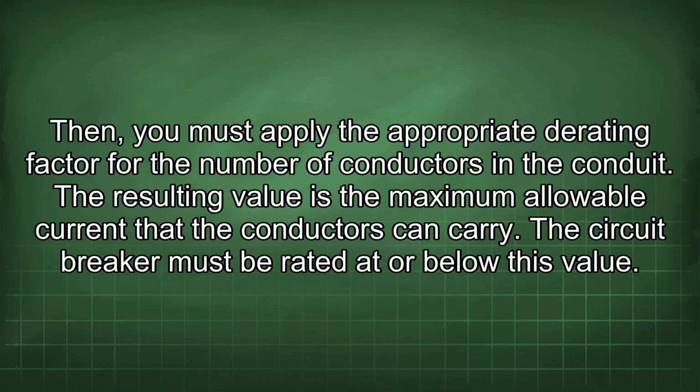Then, you must apply the appropriate derating factor for the number of conductors in the conduit. The resulting value is the maximum allowable current that the conductors can carry. The circuit breaker must be rated at or below this value.